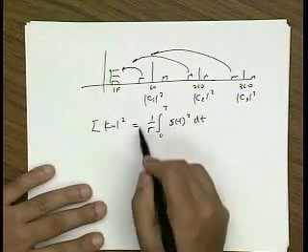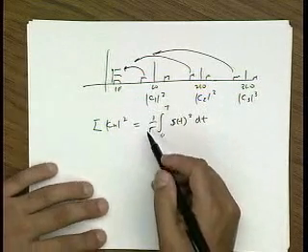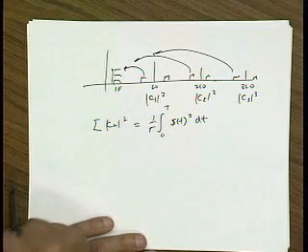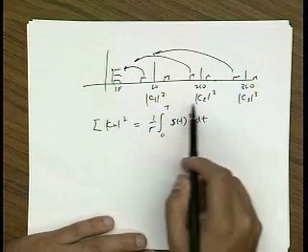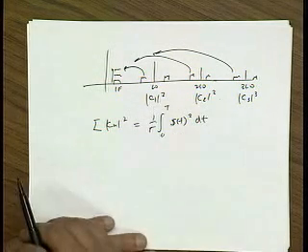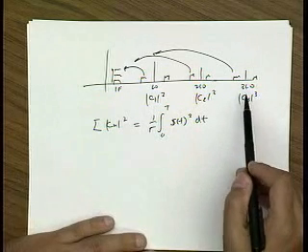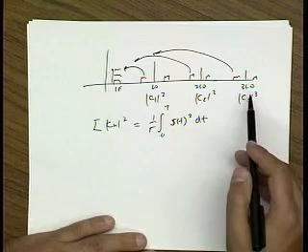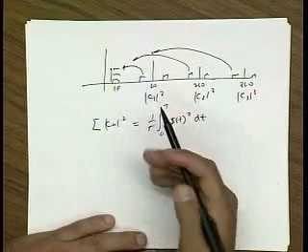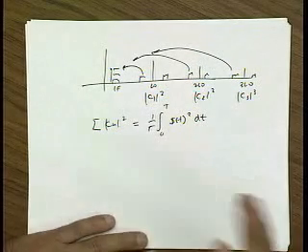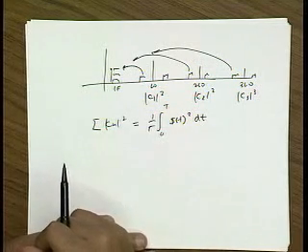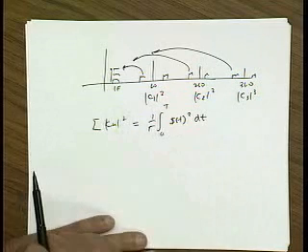And so, depending on how much energy there is in the switching waveform, that's how much noise folding you get. Okay? And you can actually calculate what's the noise contribution from second compared to first, right? So if it's a square wave, the first contribution would be from the third harmonic, right? And that is down by a factor of 1/9. It's 1/3 squared. So you see the noise contribution is about 10%. And that's the biggest contribution. Then you add the fifth. That's down by a factor of 1/25. So this converges pretty quickly for most switching waveforms.